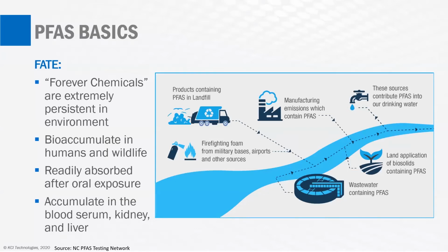Once it gets to the drinking water source and is consumed by humans, it may find its way to the wastewater stream and then into our wastewater treatment plants, where either it's going to pass through the treatment plant untreated, depending on the treatment technology in place, and go back to the drinking water source, or it is captured and transferred from the liquid phase to the biosolids, and that biosolids is land applied, it may, with surface runoff, leach from the land application site back into the drinking water source.